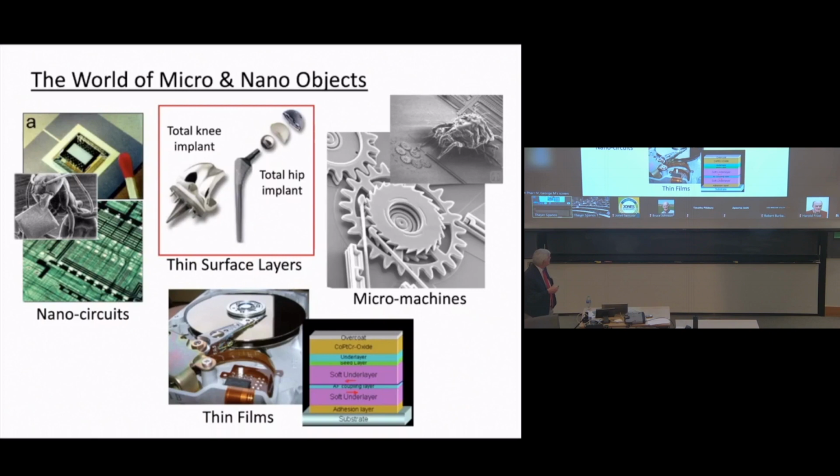But these things spin at about 3,600 RPM in a standard hard drive. And as they're spinning, you've got this read-write head that's sitting on top of the thing. That read-write head is writing the information, making a small region a bit magnetized, or it's reading it to determine whether or not it is in fact magnetized. So is it a 1 or is it a 0? And this head flies over the surface of this thing as it rotates. This head flies at a distance which is less than 5 nanometers.